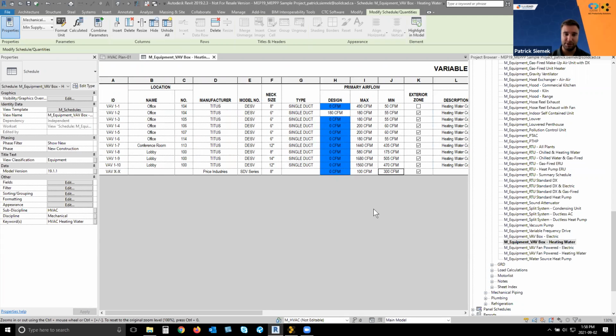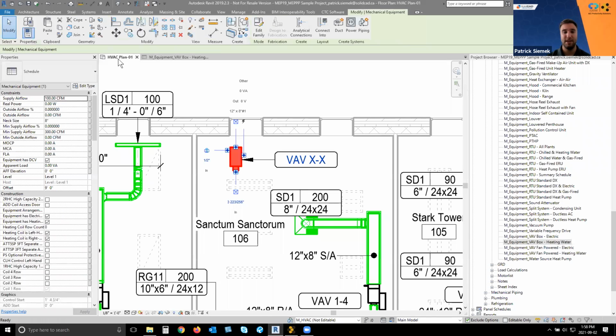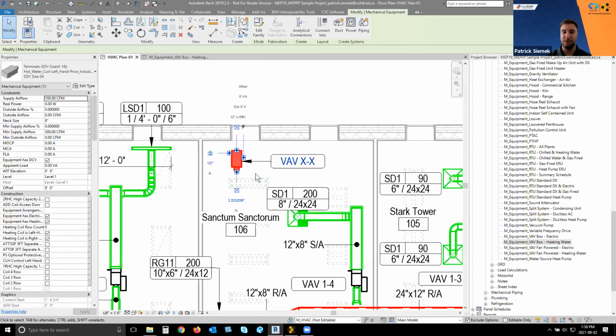Down the road, as the projects build up or as the projects end, Revit end users probably want to speak to a BIM manager saying, we need this kind of content within our projects, or we need to make sure that the content that we brought in is going to work seamlessly within our schedules. So from a BIM manager's side of it, looking at the families, we're not going to be loading it in and running the Parameter Jammer. We want to make it more robust. We actually want to modify the families initially, then load them into our project.